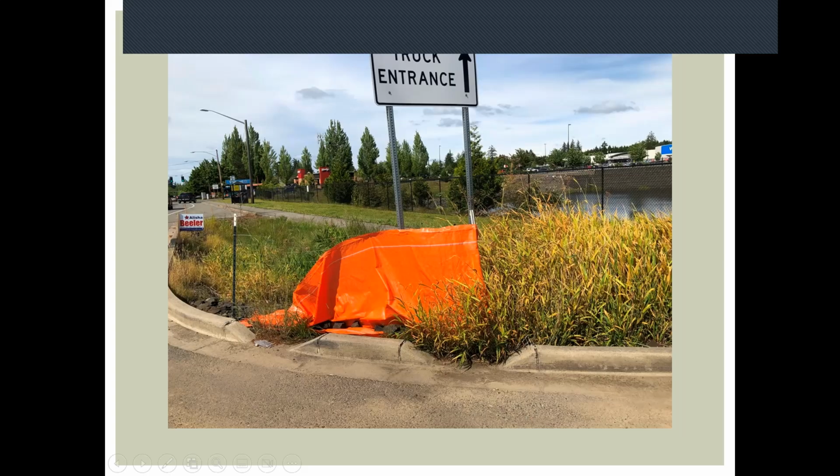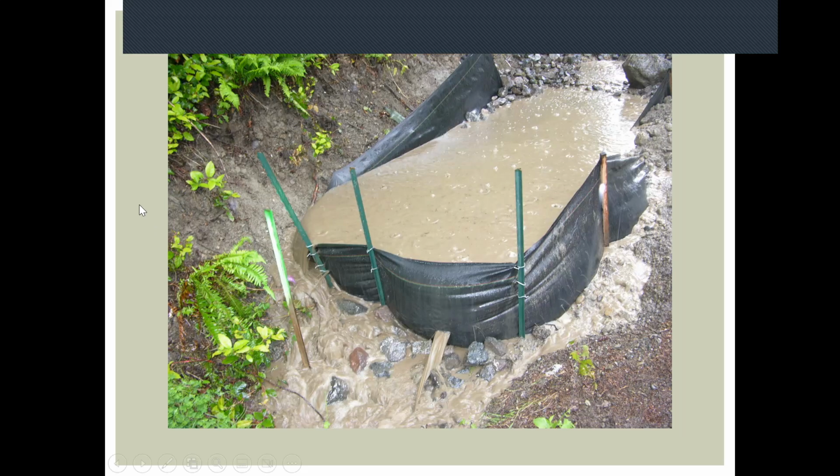Same with something like this. They're trying to protect the swale, the curb cut access into the swale. And this makes no sense. Apparently somebody didn't tell the contractor what they needed to do, where a few sandbags or some cold patch would have done the job even better. And another inappropriate use of silt fence.